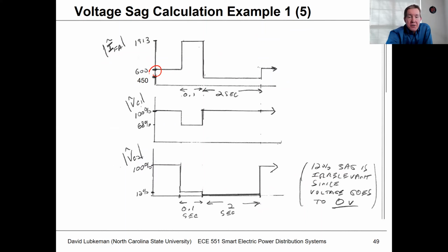Then when the fault occurs, basically what I'm going to see is the combination of the fault current and the load current. Now, since the fault current is generally a lot greater than the load current, I typically just assume what that monitor sees is the fault current. If you want to make this a little bit more accurate, you can put the load current back in, but keep in mind that there's a severe phase shift on the current. Most of this current's reactive, most of the load current's resistive. And so the reactive current's dominating in this case for the magnitude.